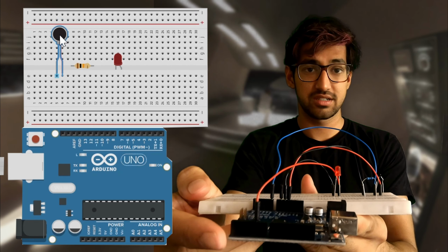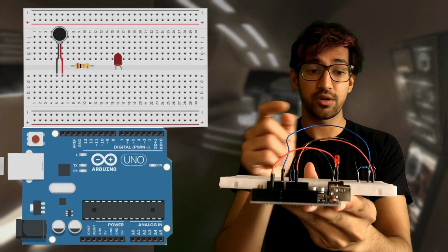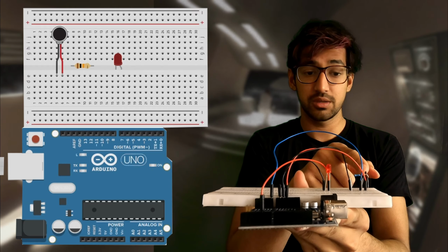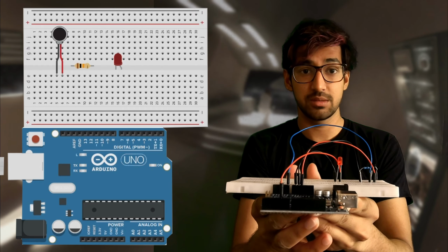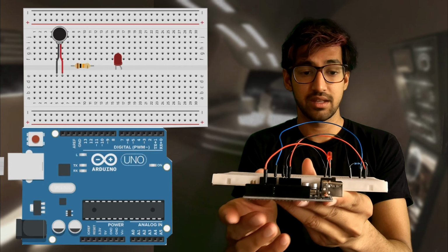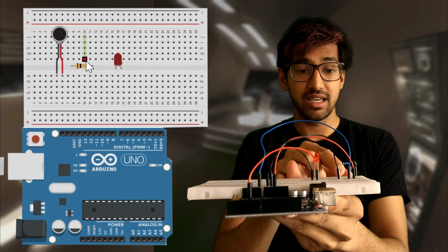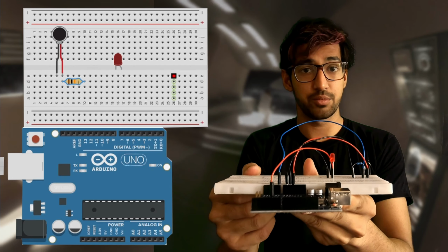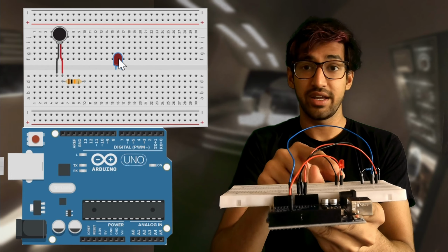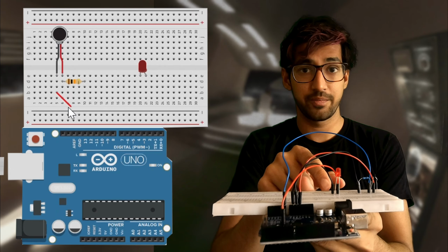Let's see how the connections are done. Connect your thermistor to 5E and 7E. Make sure that the positive of the thermistor is connected to the positive powering line. Otherwise, you have a possibility of burning the thermistor. Connect a similar value resistor, in this case a 10K resistor, to 7D and 11D on the breadboard. Connect a red LED to 20E and 22E on the breadboard.